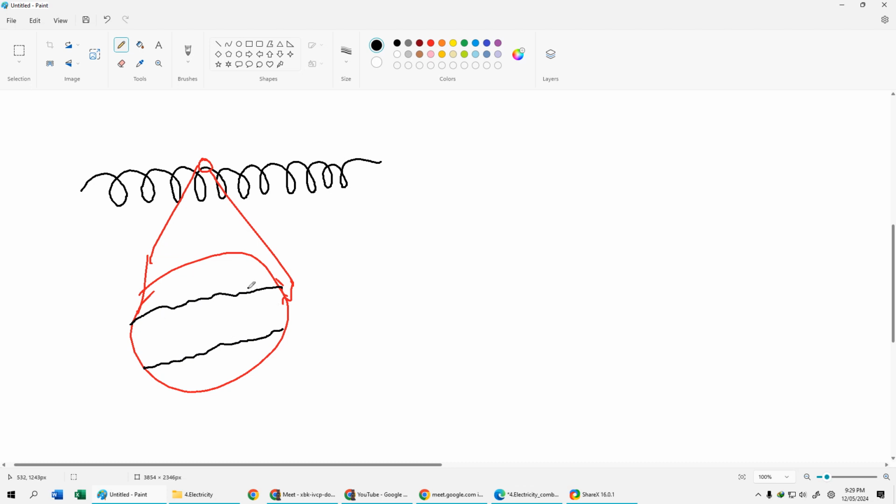Now because this wire is not uniform cross section area everywhere, it is impossible to achieve truly uniform cross sectional area. This would necessarily mean locations where we have a little bit of small area will have a bit large resistance, and location where we have a bit of a thick area will have a pretty small resistance, because we know resistance is proportional to 1 upon area.